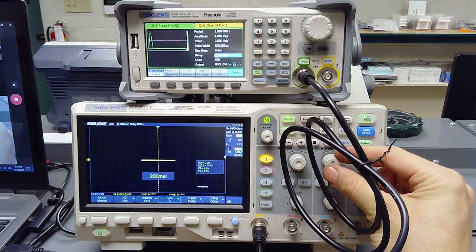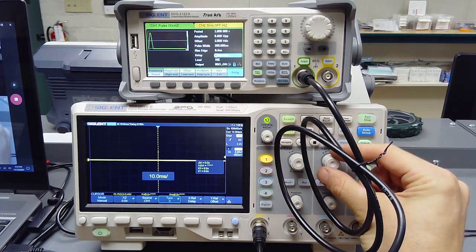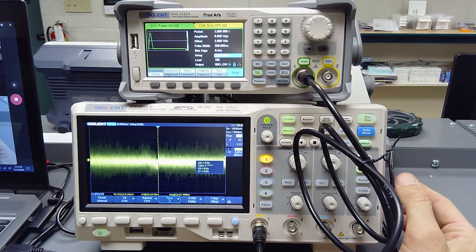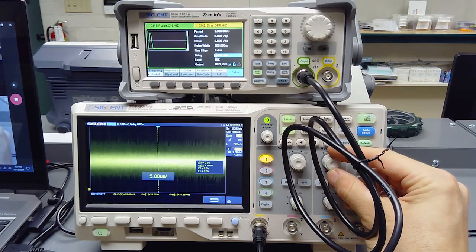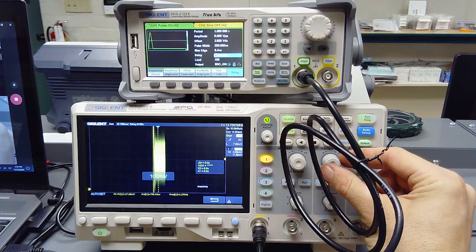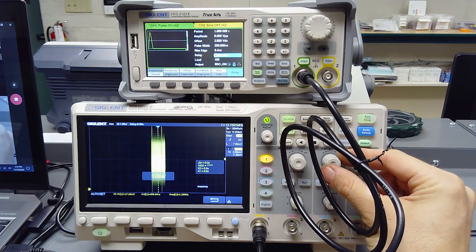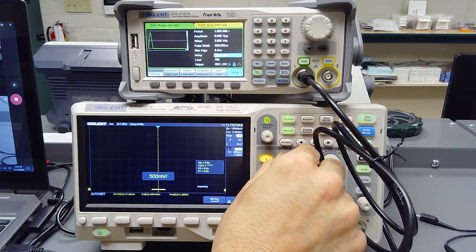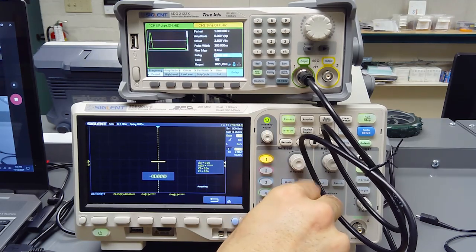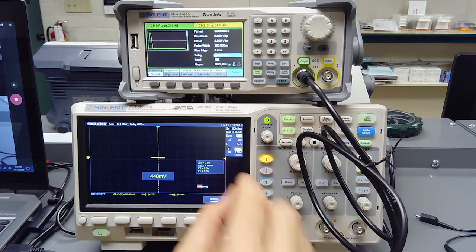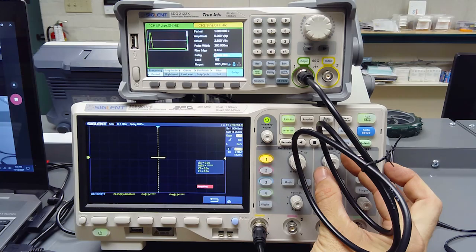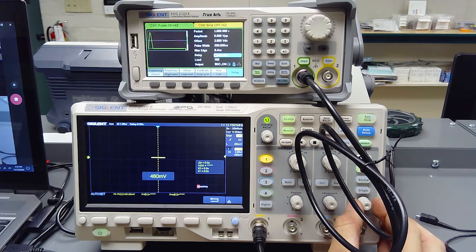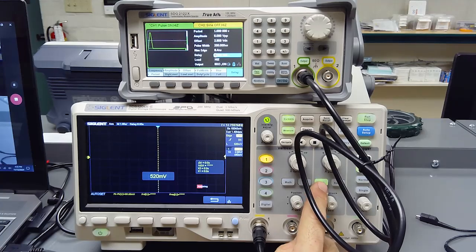And so let me zoom in here. Let's try auto. Okay, just finding something. Let's set this to something more reasonable, like 2 volts. Let's move it up to the middle of the screen. And now it's a little hard to find the signal, so what I'm going to do, this level is set to a decent value, but let's just press this roll button and see what comes up.